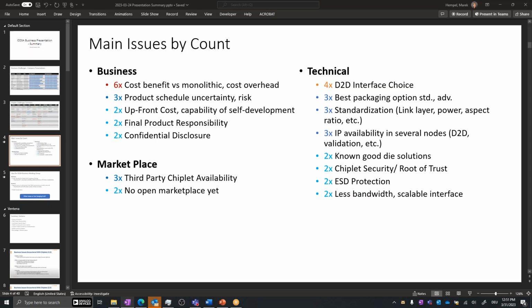And how to test it. So they were finding, and I've heard this from a number of people, that the cost of implementing a die-to-die interface, because inherently a die-to-die interface starts running at 4 gig and can go up to 16 gig per link, may require a more expensive substrate.